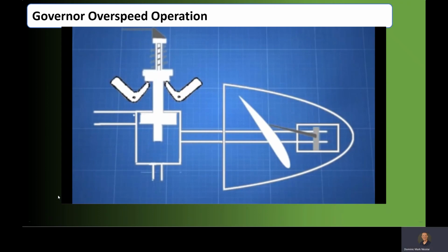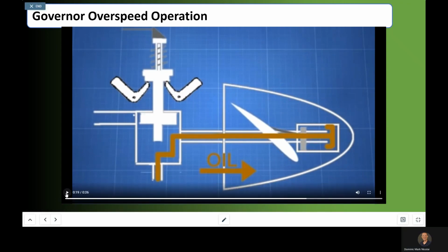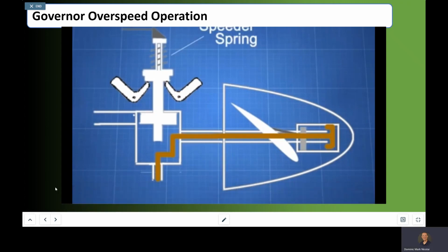The pilot valve is now allowing oil to come into the system and make that blade angle greater. So up here is a little piston inside that spinner, and that piston is connected to the blade angle. That's what's moving. More oil goes into that, moves that piston to a much greater blade angle.